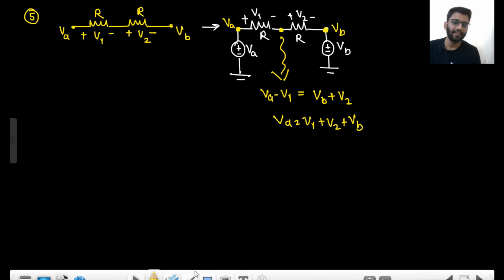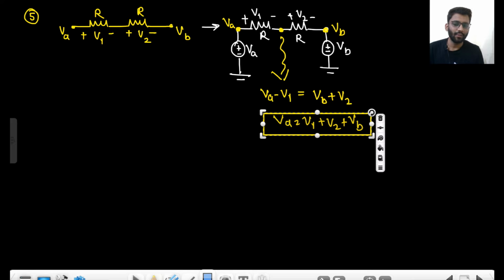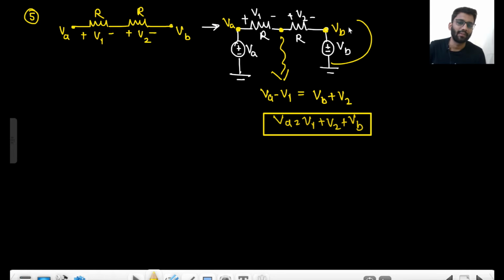So basically, that thing that I told you about starting from a point and then jumping, you can do for any arbitrary point. You start from here, 0 minus VB, plus V2, plus V1. Like what I am saying, you start from here, VB, then again jump, plus V2, then again jump, plus V1.